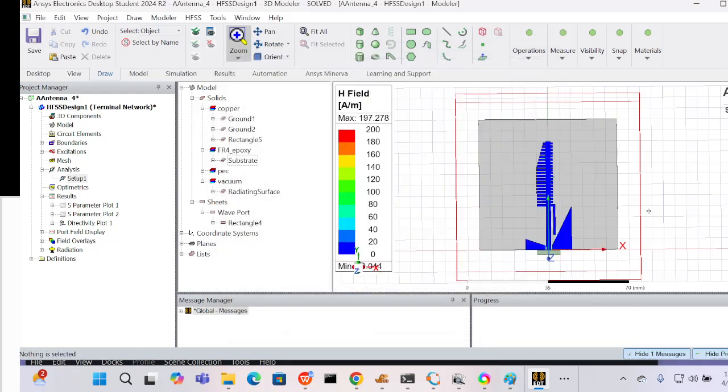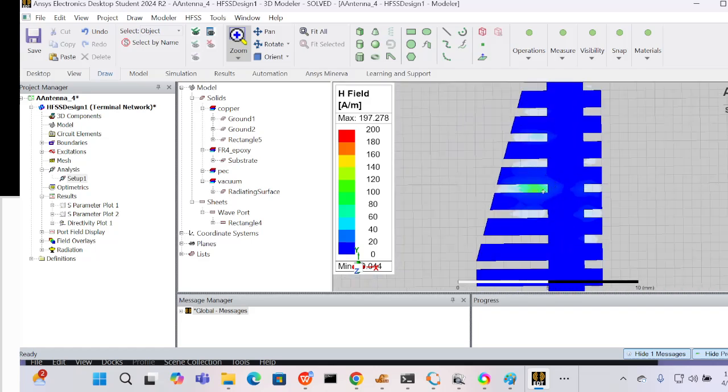Yeah, you will end up with a plot, but the plot is not clearly visible enough. And you need to lower the upper limit of the magnetic field. In this case, I would say, yeah, I can see there's some color division here. Yeah, I can zoom in, do it again. Zoom in, yeah, you can see that only this region.